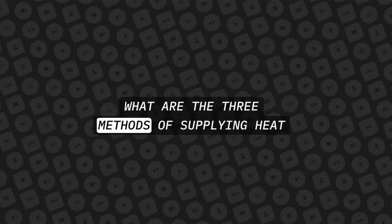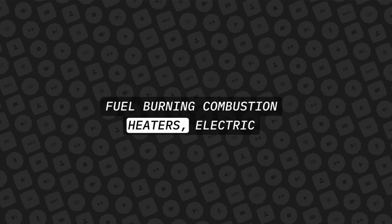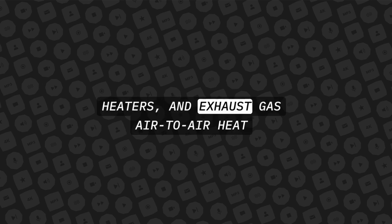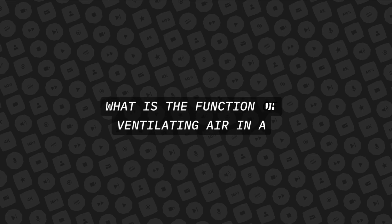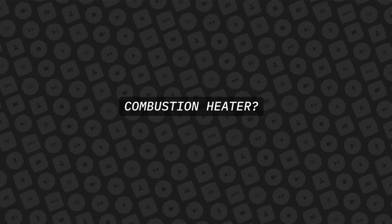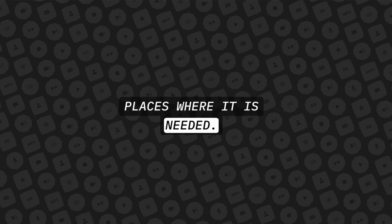What are the three methods of supplying heat to the conditioned air when the heat of compression is not sufficient for this purpose? Fuel-burning combustion heaters, electric heaters, and exhaust gas air-to-air heat exchangers. What is the function of ventilating air in a combustion heater? Ventilating air is used to carry the heat to the places where it is needed.